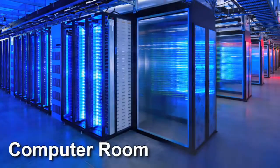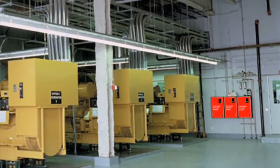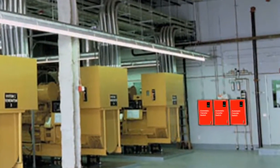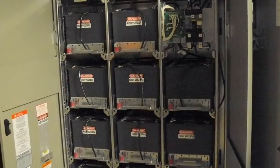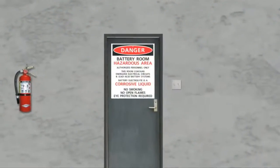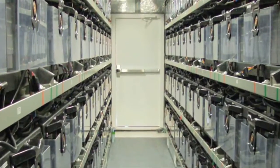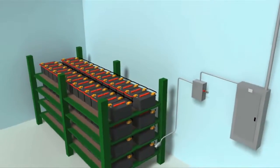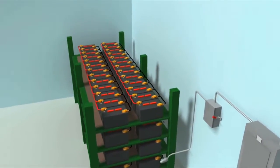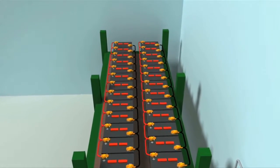In larger facilities with higher emergency demands, you may find several generators along with several automatic transfer switches. Auxiliary power is also stored in a battery bank. A battery bank is located in a designated room with battery racks that house batteries that are connected together. They are being charged 24 hours a day. These batteries are connected together to provide a specific voltage for a certain period of time.